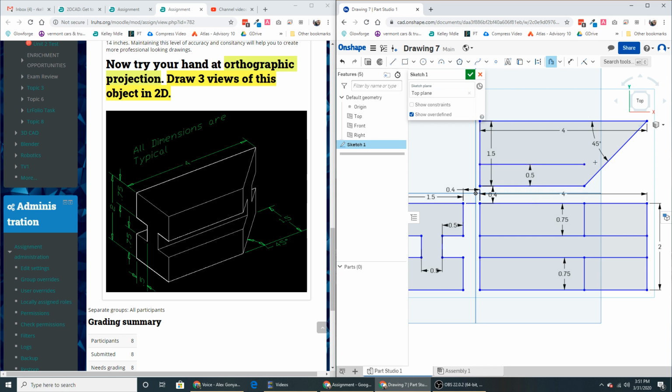Okay, now it just needs to stretch out the rest of the way. There is an extend tool here, and I can click on the object and extend it to there. Press escape. If I were to come straight down, that's going to tell me where that edge is. So I'll grab the line tool, hover over that dot, make sure I've got that extending yellow line following me, and then click and click. Press escape. Okay, I've got this edge here.